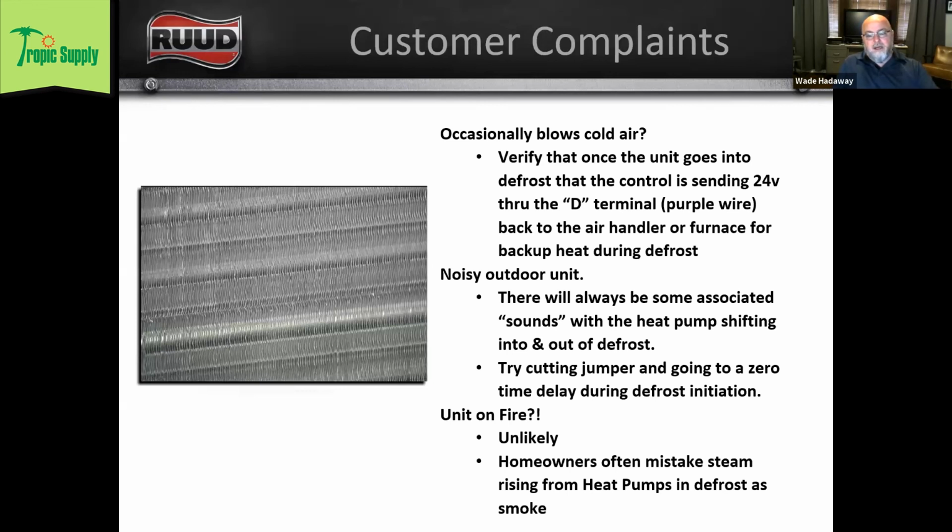Noisy outdoor unit, especially if your customer or the homeowner has never had a heat pump before. There's always going to be associated sounds and noises when a system goes in and out of defrost, or when we energize the reversing valve to initiate a call for heat.